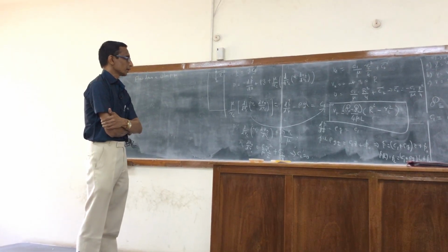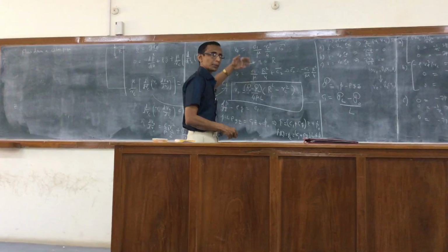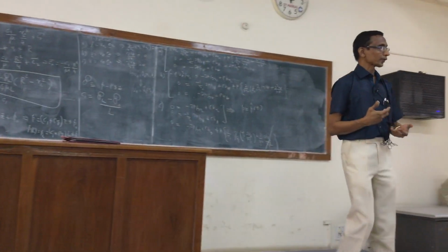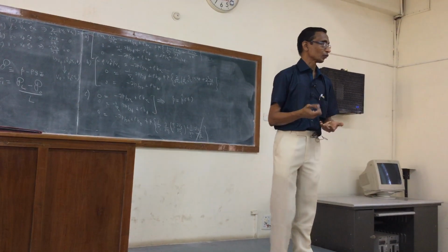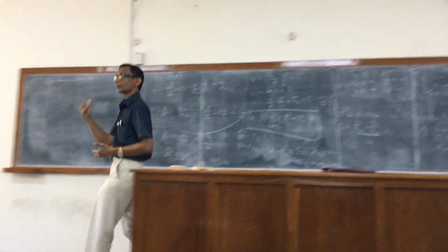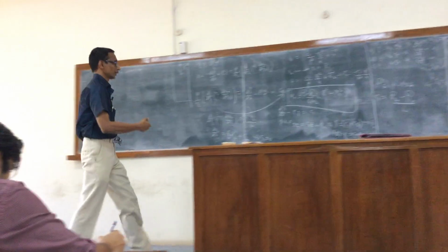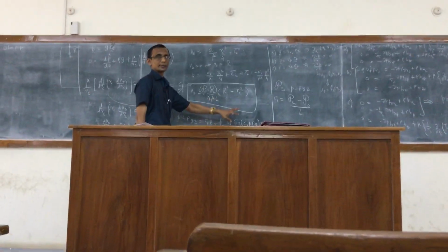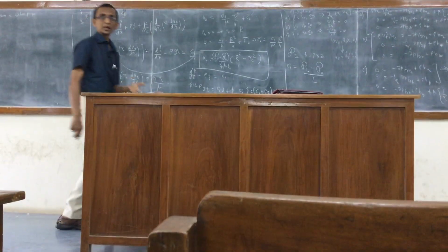Relation, and it is given as if this can be regarded as a pressure drop. This is the modified pressure drop, right? If that is positive, then it leads to a flow in the positive Z direction. That's how you have to view it. The whole velocity profile is given in terms of the modified pressure difference per unit length, and of course divided by viscosity and so on. So we get the parabolic velocity profile that you are all familiar with.